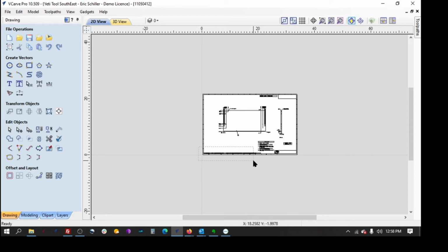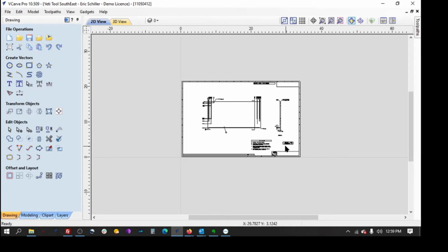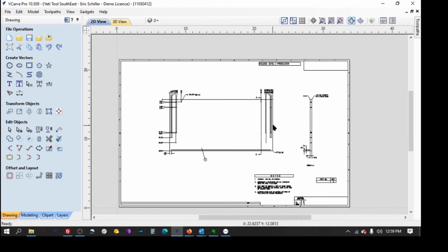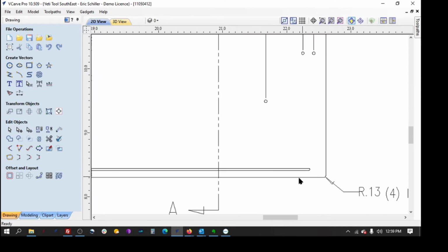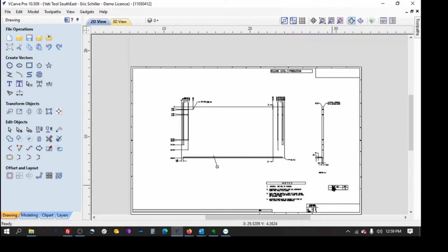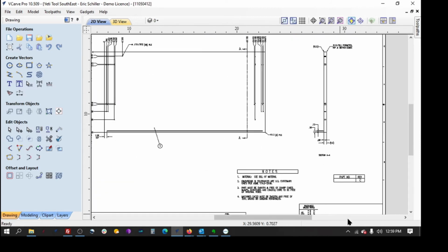This bottom line had information about the product. This last line of the instructions shows the part number. I'm going to scroll in just a tiny bit just to be able to get it. So that had the production number. And this says production notes, and there's information about, I can scroll in at this point. There's some holes that are going to be drilled. It's a 0.17 hole going 3/4 of an inch deep. There's 28 of them. There's a dado here at the back, and a 0.13 radius on the corners. So basically, that's all I need to know. All the other information I don't need.